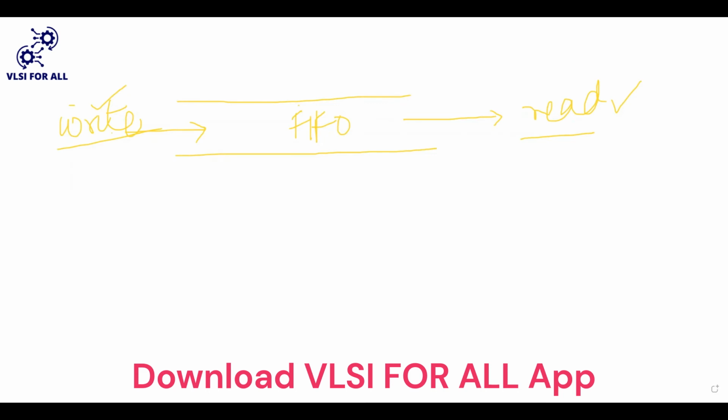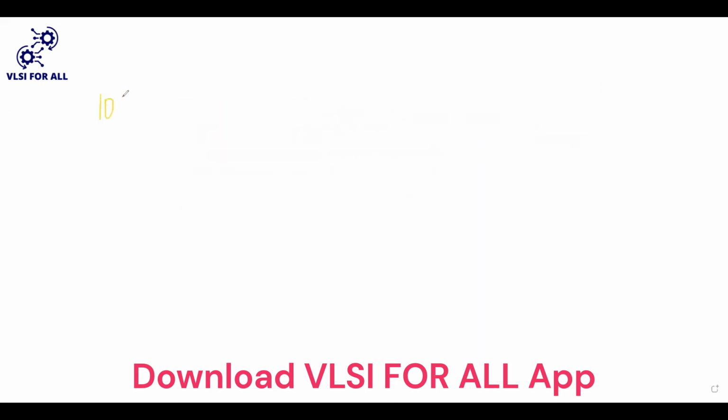If we change the clock for the read and the write enable signals, then it would be an asynchronous FIFO. So what is the difference between $stop and $finish? Suppose in our program, we need to understand the execution. Suppose for every 100 nanoseconds, the values are getting changed.